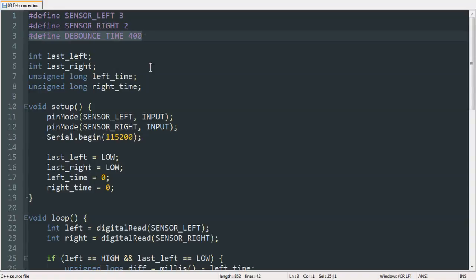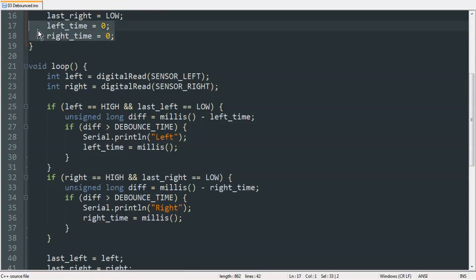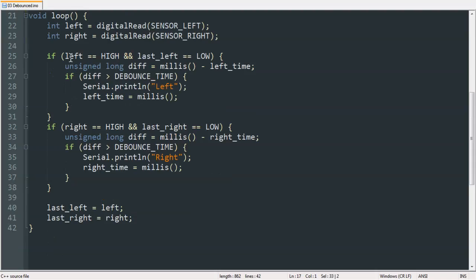That is, we're actually going to assume a little bit of delay before we see the pedal again. This tends to be a fairly good assumption because you can't pedal at lightning speed, and with this, we can effectively filter out all the bouncing because those tend to happen very quickly, one after another. To do this, we introduced two more variables to keep track of the last time we've seen the left and right pedals. We initialize them to zeros, and every time we encounter the same sort of condition, that is, when one of the sensors reads high when it was previously low,